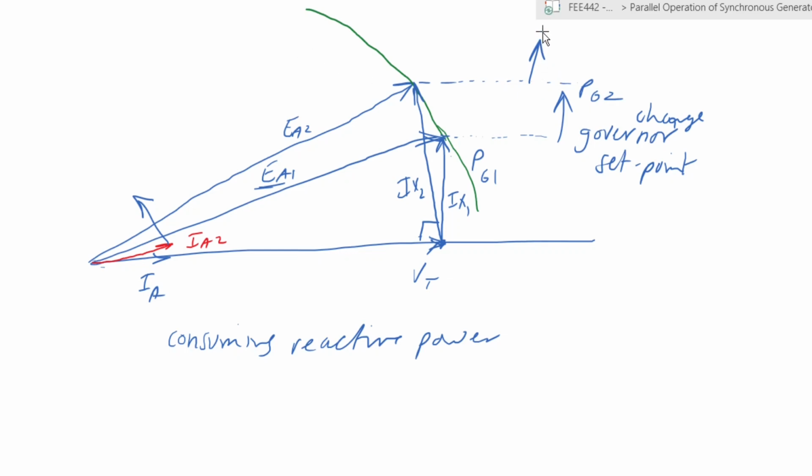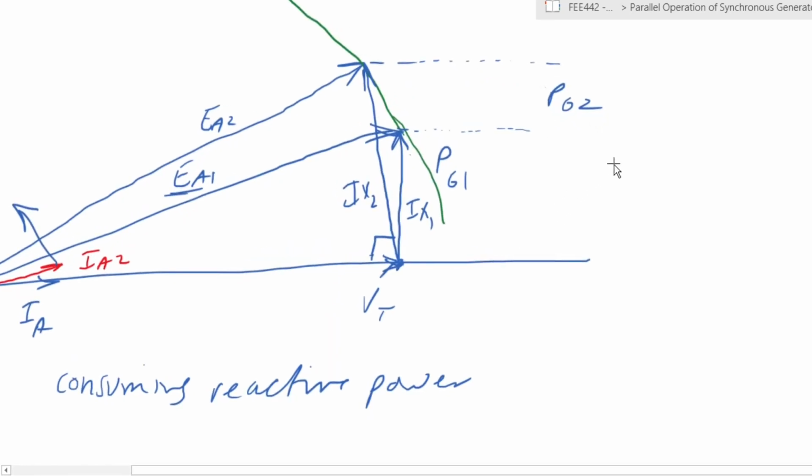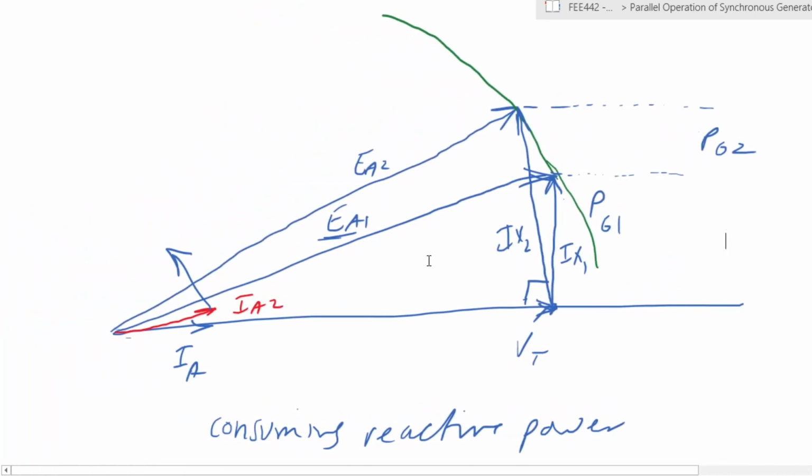So I will try to demonstrate that on this same diagram. Try and delete some of these. So put this here. Now, if we have your system looking like that, we have increased our power from the initial point, which is PG, to PG2, but we realize that we are now consuming reactive power. Our power factor has gone off. So we want to return it back to this point, which will enable us to have the PG2 that we want, but at the same time, we will have a good power factor. So that would then mean you have your EA3 now moving across to PG2.